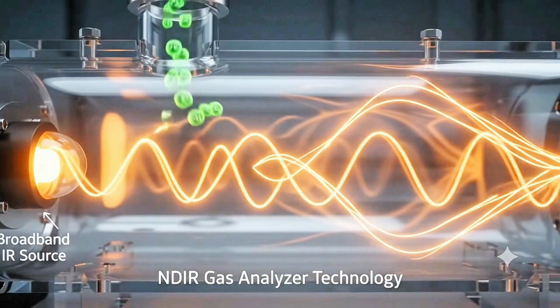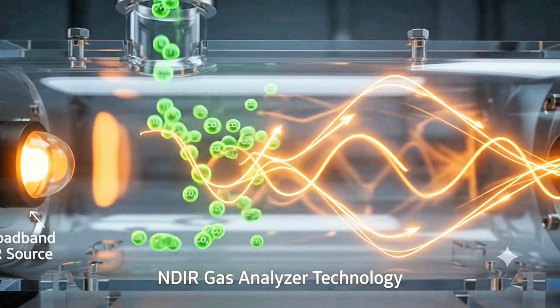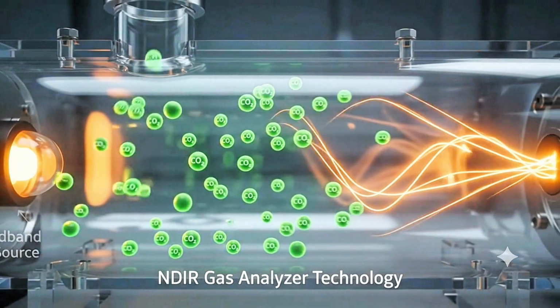And if the analyzer itself flags a fault, like a low reference signal or a chopper fault, that's telling you the problem is inside the optical bench itself, not the process. That distinction alone will save you a lot of troubleshooting time on shift.